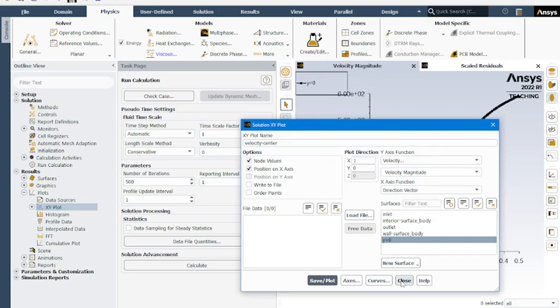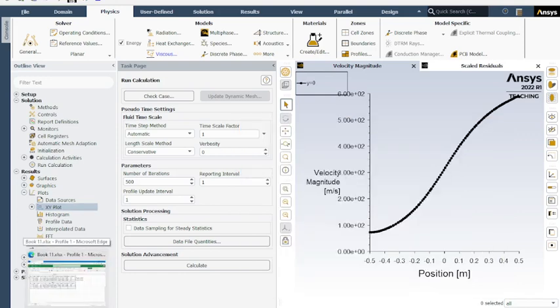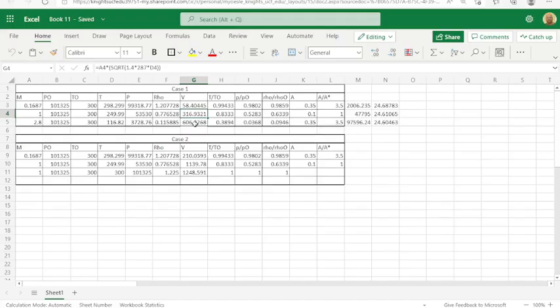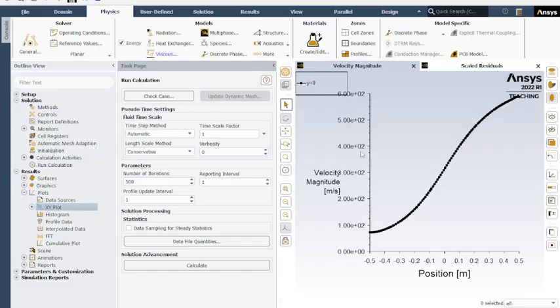Now since it increases the whole time, we can tell that we're hitting Mach 1 right at the throat region at x equals 0, the middle of our CD nozzle. And we'll compare this with our calculations for our velocity. We had 58.4 meters per second at the inlet, 316.9 at the throat, and 606.6 at the outlet. So let's see how that compares here. We had 58, around 300, around 600 meters per second. So it looks like everything's adding up to what we calculated before.